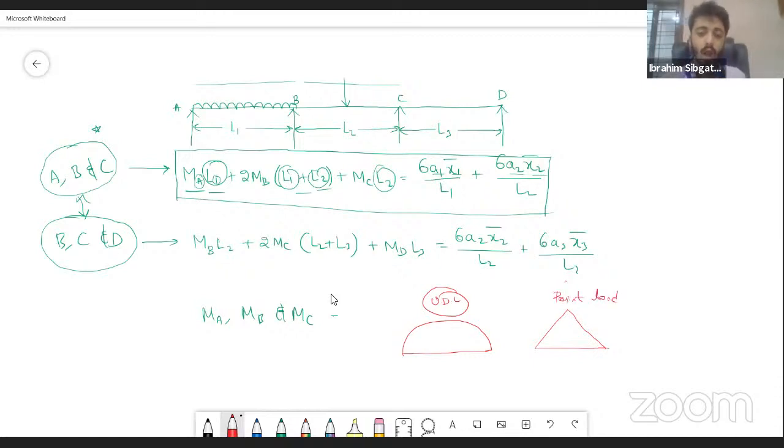Okay, so depending on how this area looks, how these shapes look, we will be calculating the areas. A1 and A2 are the areas of the bending moment diagram under that specific span. So let's say in this case for span AB, once we are done calculating, we will get a diagram under this span. And then when we are calculating span BC, we will get one more diagram under this span.